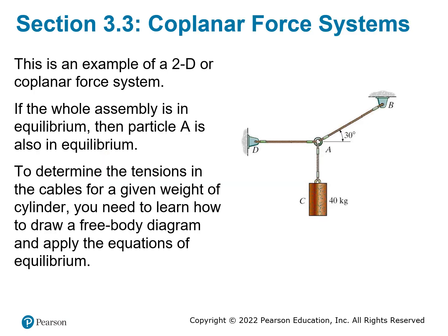Now I hope that you understand how to make a free body diagram. Always when you do a free body diagram, you have to select the point that you want to isolate, and then you identify the forces that connect to that point, and you do the analysis based on the configuration of the forces applied to that point.